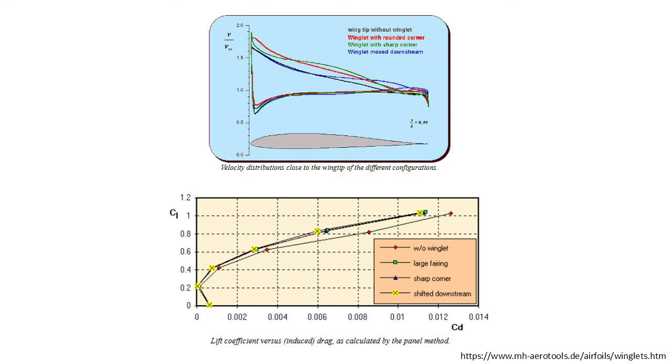We can use a winglet that extends straight up from the wing with no issues, but we can also shift the leading edge of the winglet back as if the winglet had some sweep to clean up the velocity distribution near the wingtip and overall maintain a clean and minimum local pressure rise on the adverse side of the airfoil out towards the wingtip.